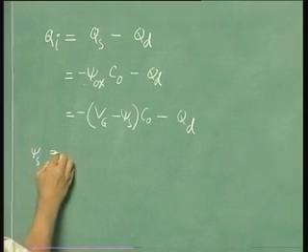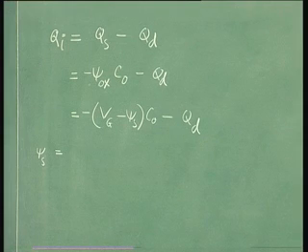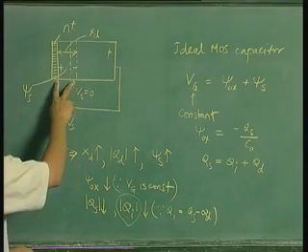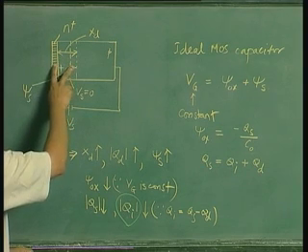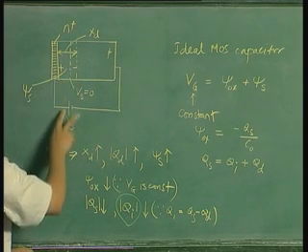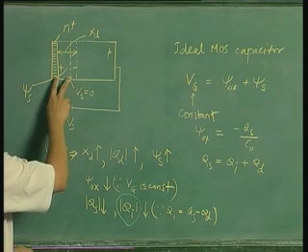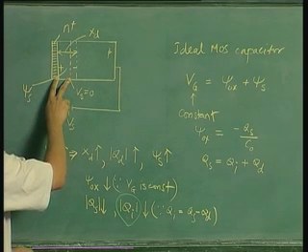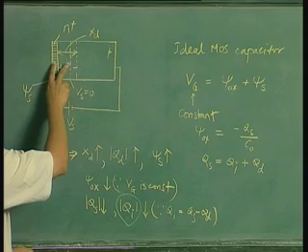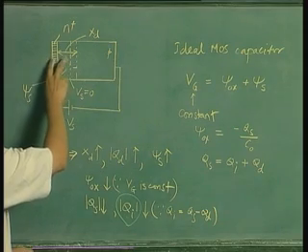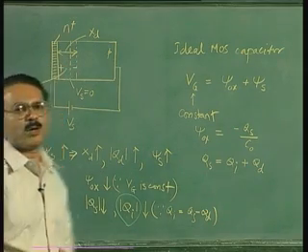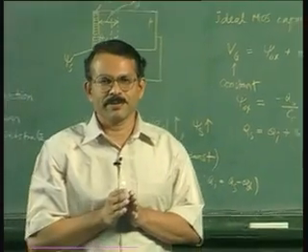Psi s is equal to the potential drop across the n plus p junction, the internal potential drop. The external applied reverse bias is Vs, but when Vs is equal to 0, you still have a depletion layer, because you know that there is a psi s when you create an inversion layer, and that psi s is equal to phi t or twice phi f.